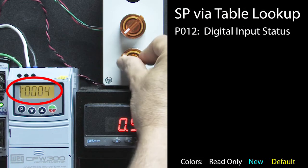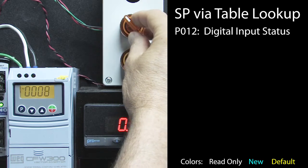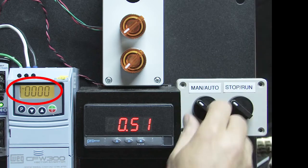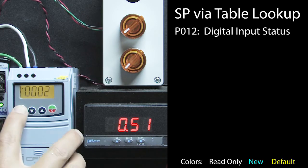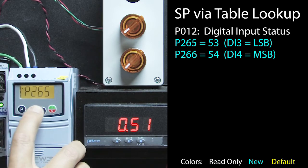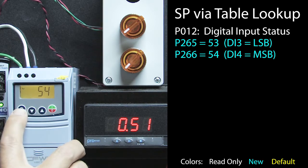Sure enough, this switch controls digital input 3, and this switch controls digital input 4. Perfect. Looks like I wired it correctly. I'll turn both switches back off and enable auto mode so PID automatically controls the motor when we switch to run. Let's go to parameter 265 to tell digital input 3 he'll be the least significant bit of our selector, and parameter 266 to tell digital input 4 he'll be the most significant bit of the selector.